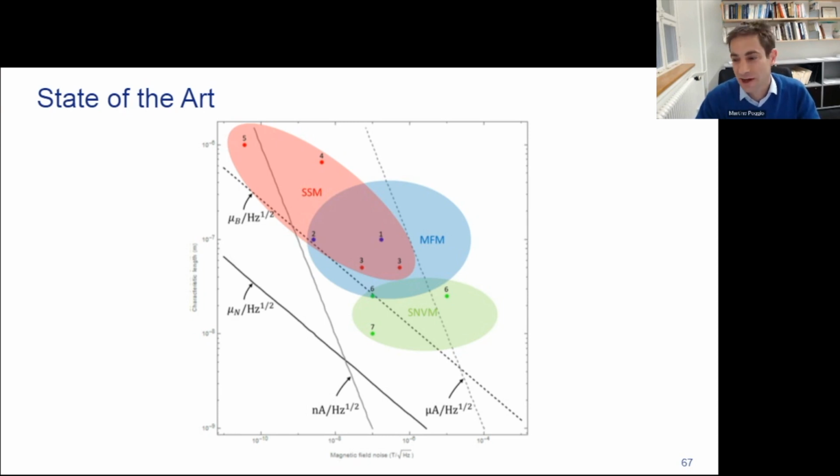So the sensor is essentially like a very, very good bandpass filter and only reacts at certain frequencies. For the SQUIDs, I think the bandwidth is really very good. You need to stay away from DC, where you have a lot of 1/f noise, but once you get into the tens of kilohertz or beyond, you should be in the white noise limit and have very low noise, and essentially be unlimited in the frequencies that you can measure. For NV magnetometry, you can measure certainly at DC and at higher frequencies. They use pulse sequences, some kind of Hahn or spin echo-like pulse sequences, to reduce noise and get the best sensitivities, and that limits the frequencies that you can work at a little bit, but in general they have more bandwidth than mechanical sensors. So I would say bandwidth is best maybe for the SQUIDs, then for the NVs, and worst for the force sensors.